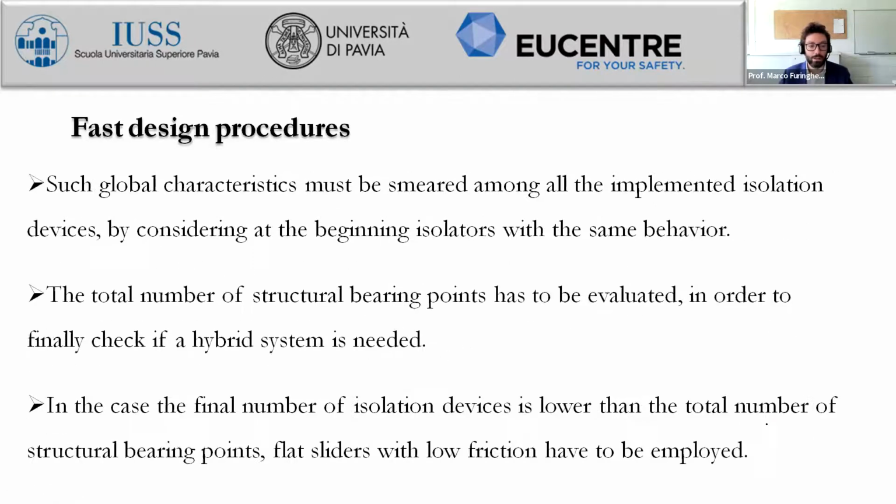Then we have to smear all these characteristics among all the implemented devices, and I just want again to highlight that they will be smeared just among the isolation devices and not also to flat sliders when we have to consider hybrid solutions. And at the beginning, we just assume that we consider isolators with exactly the same behavior.